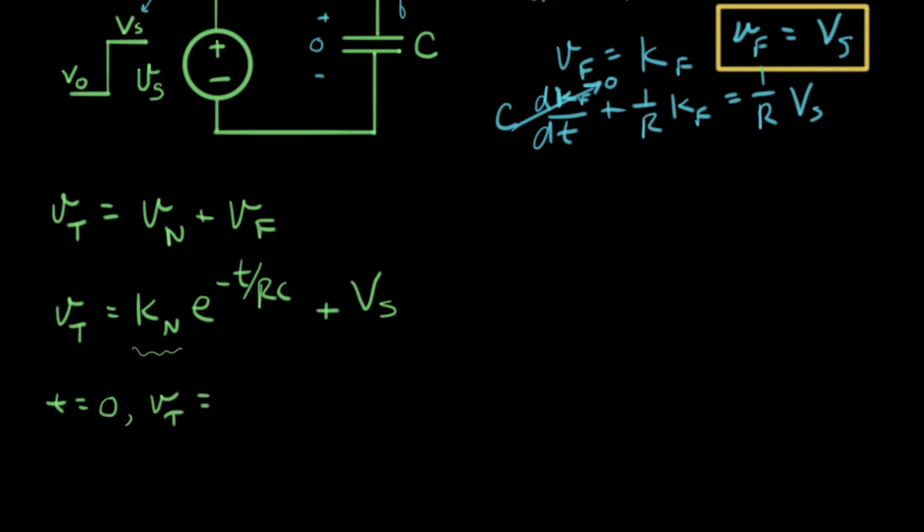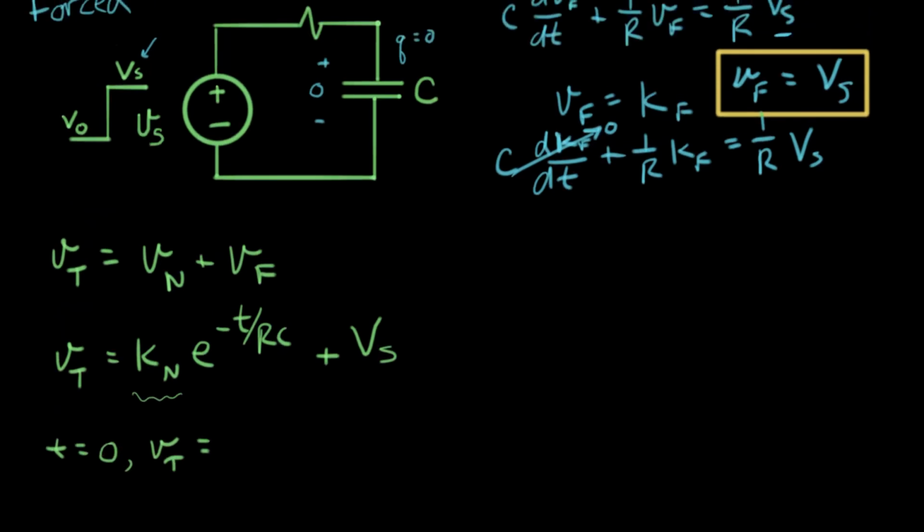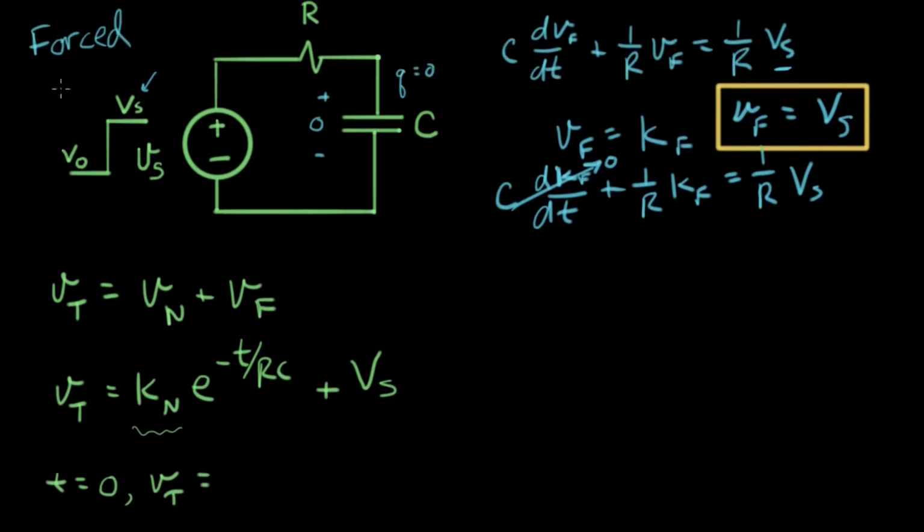Let me go backwards a little bit. Let me go back here and use this diagram again. This was the forced response, so we're not going to use that right now. We're going to use this, which is now the total circuit all assembled together. And we have to figure out what is the actual initial charge on here. And if we recall, the initial charge on here was V naught. That was this value here just before time equals 0. This was the value of the voltage on that capacitor. So I can fill that in here, V naught.